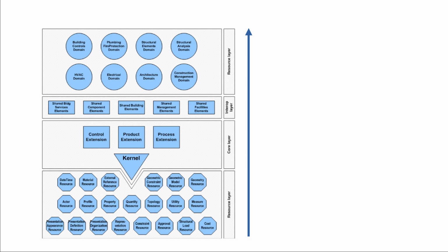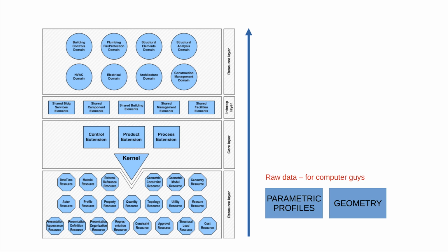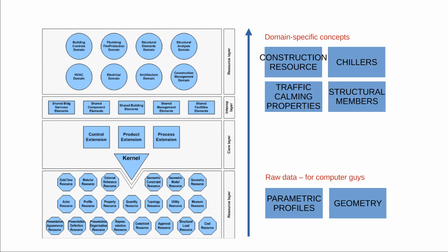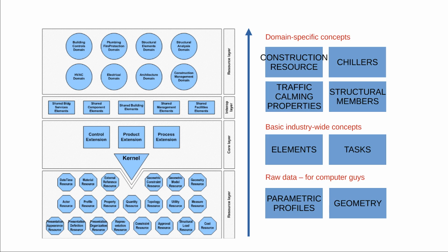And for humans, there's an alternative way to categorize these IFC classes. An alternative categorization method is to use these 4 main groups. Within these groups, they then have subcategories of more classes within them. And these categories are designed for different types of audiences to understand. So at the bottom, we have classes that are catered for really technical people because they are the fundamental building blocks, like classes that represent geometry. And at the top, we have categories which are most relevant to very specific disciplines, like HVAC classes or electrical classes or structural classes. And in between, we have classes that are shared across multiple disciplines.